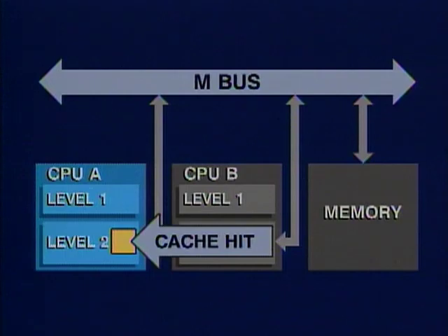You may have noticed that during a cache memory write cycle, the CVAX did not probe the Level 1 cache first. This is because the Level 2 cache needs to be updated to ensure cache coherency. Whenever the Level 2 cache is written to, the corresponding entry in the Level 1 cache is invalidated. To update the Level 1 cache first would be a waste of time.